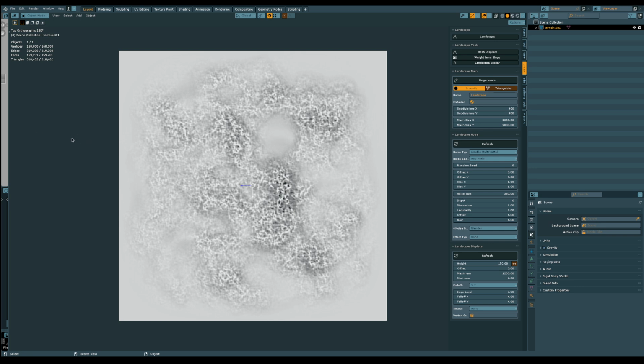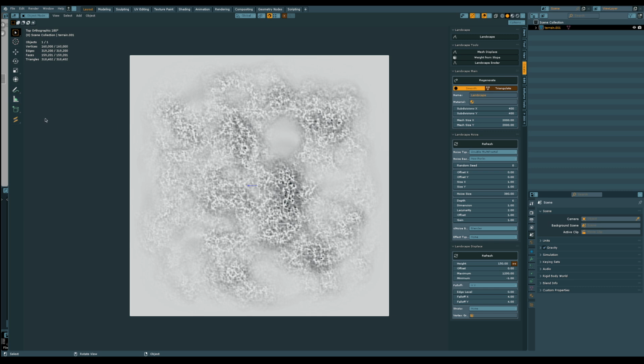So press T on the keyboard to display the toolbar in here, and then select Annotate. From Placement, select Surface, and maybe you want to increase the radius and the factor so you don't have a hard time seeing what you're doing. All right, let's draw the road. You don't have to be very precise. Just go with it. If you're unhappy, press Ctrl Z to undo, and start over.